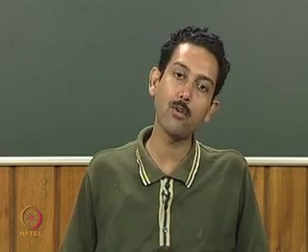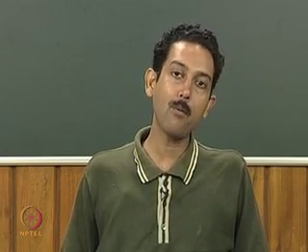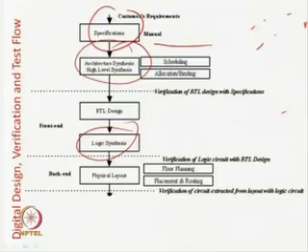Adder at the RTL level is A equal to B plus C. But when we go to the gate level, A plus B will give the sum as A XOR B and the carry as A dot B. So, we are going to the gate level. Logic synthesis actually converts it into the gate level. Now once everything has been done at the gate level, your circuit has to be fabricated and sent to the market.